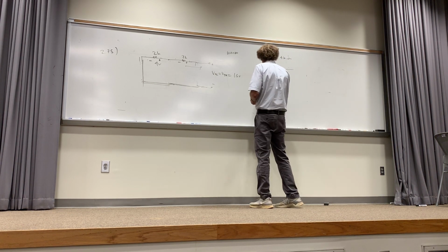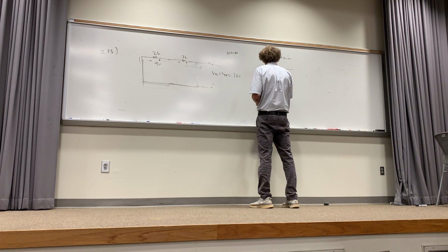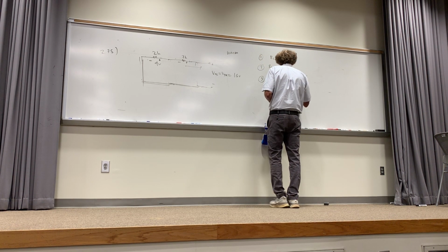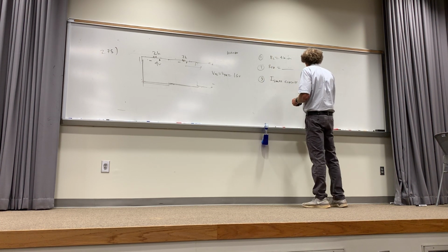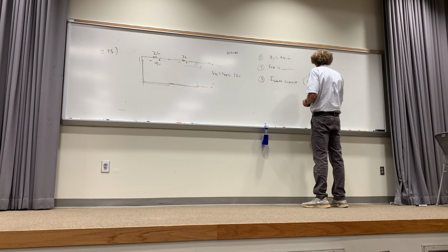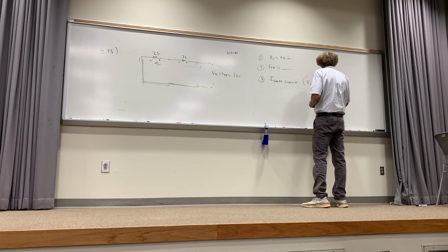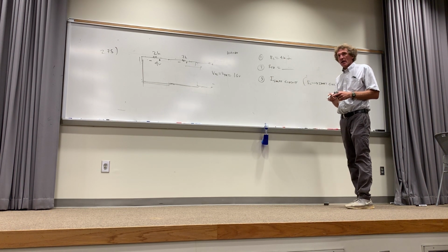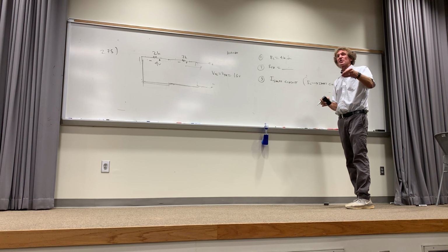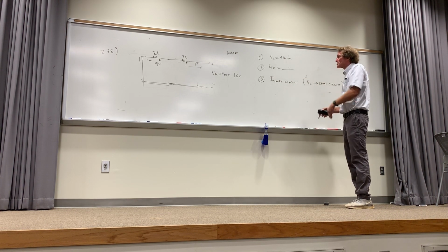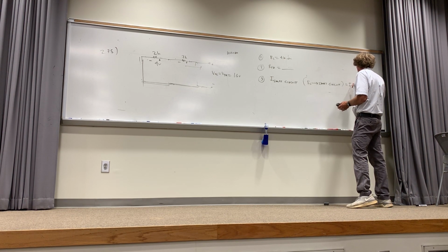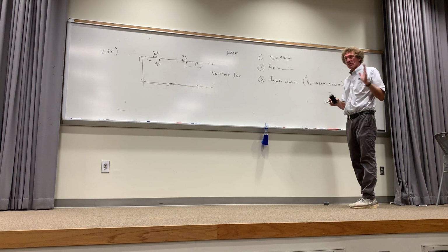The third thing is, now we find I short circuit. Which means we replace our load with a short circuit. All right? And instead of finding the open circuit voltage, we find the short circuit current. Now this is just I short circuit, and I'm going to do a problem. Do y'all understand me? This is the difference.